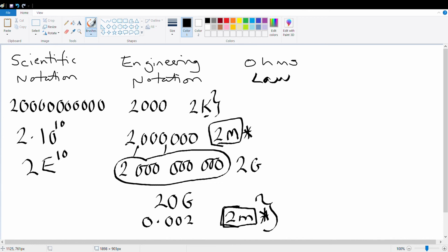And that brings me to Ohm's law. Now, the way I used to remember Ohm's law is, maybe it's a little silly, or maybe it will help you. I remember the top being V, because the top you could almost make a diamond, and that meant that IR could go here, and it didn't really matter if the R is on the left or on the right. But that helped me because then I always knew that if I was looking to get current, which is I, that would be voltage divided by resistance. And when you get one, you get the others, right? Or resistance would be voltage divided by current. So this is Ohm's law.